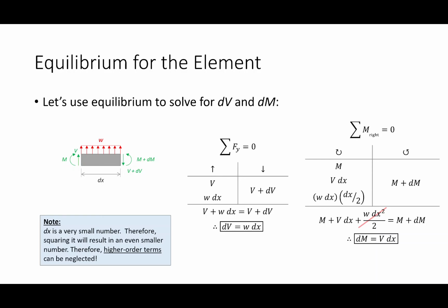That is great for spot checking these types of problems, but that's not great for what we're after. What we're after is we're given the load, and we're trying to find the shear. So how do we find the shear? We integrate. Does that make sense? And similarly, moment is going to be the integral of the shear.